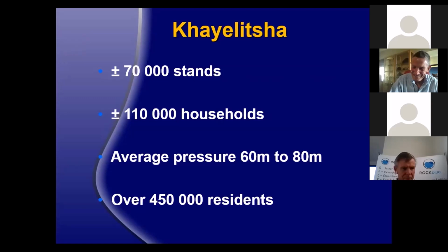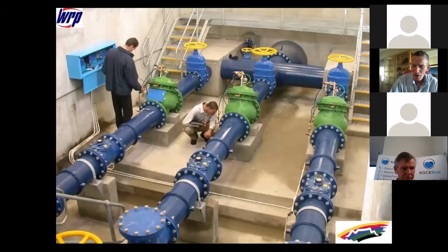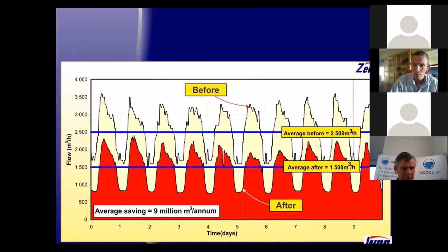Good. Okay, Chris. I'm just going to run through the 3 big installations just so you can see what they look like. Kailicha is one of the first of the big installations. That's it there with 3 valves. We used a manifold system to cut down on costs. It's much cheaper to have 3 small valves than 1 big valve.